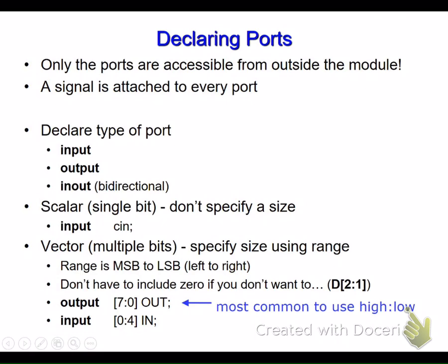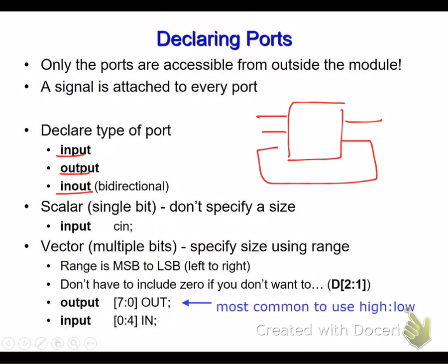You can also declare input, output, or input-output, bi-directional, meaning that if you have a block like that, you might have inputs, you might have outputs, but also input-output, where the output can go back to the input like a feedback, yes? You have to have a description for that, and this is inout, but we will rarely use it. Very seldom will we use something like that.